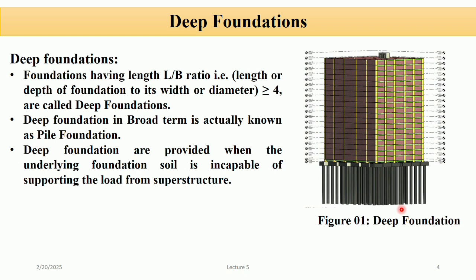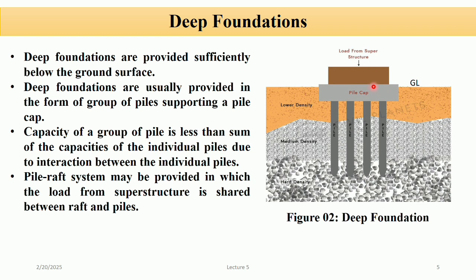We provide the deep foundation when the foundation soil is incapable of supporting the structure load. Deep foundation is provided below the ground level and it is provided in the form of a pile group. The capacity of the group of piles is not equal to the sum of the capacity of the individual piles because of the interaction of piles. So sometimes we provide the piled raft system.